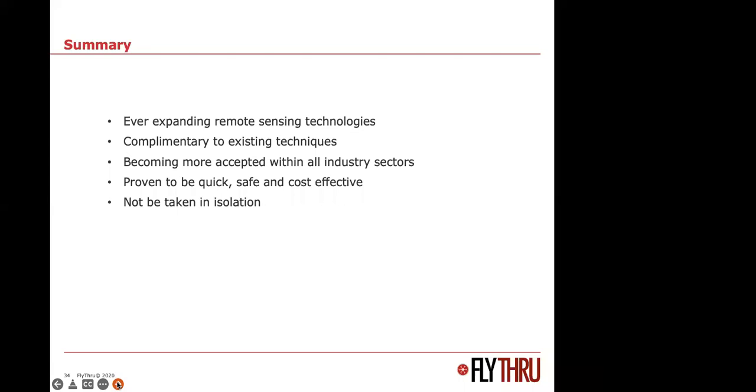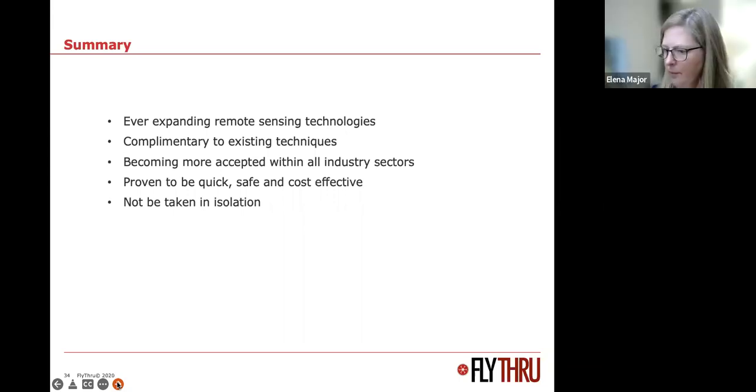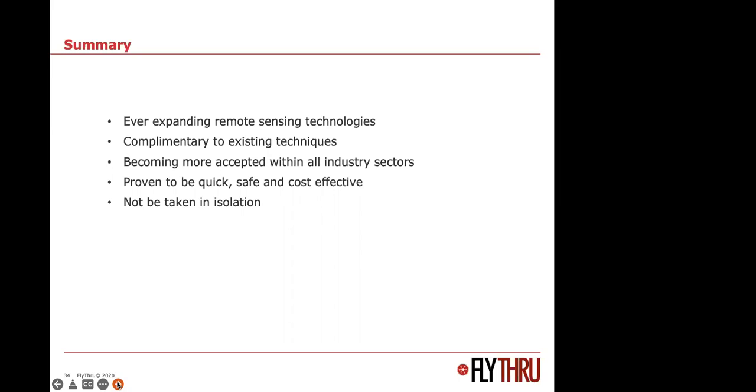You have certain restrictions on you in order to fly. So you're not allowed to go within 50 meters of people or uninvolved persons. Unless there is specific signage in a public space saying you can't fly drones, so there is a local bylaw, and there are lots of local bylaws in and around London especially saying drones are not permitted to be flown. As long as you're in an open space and give yourself 50 meters away from other people.